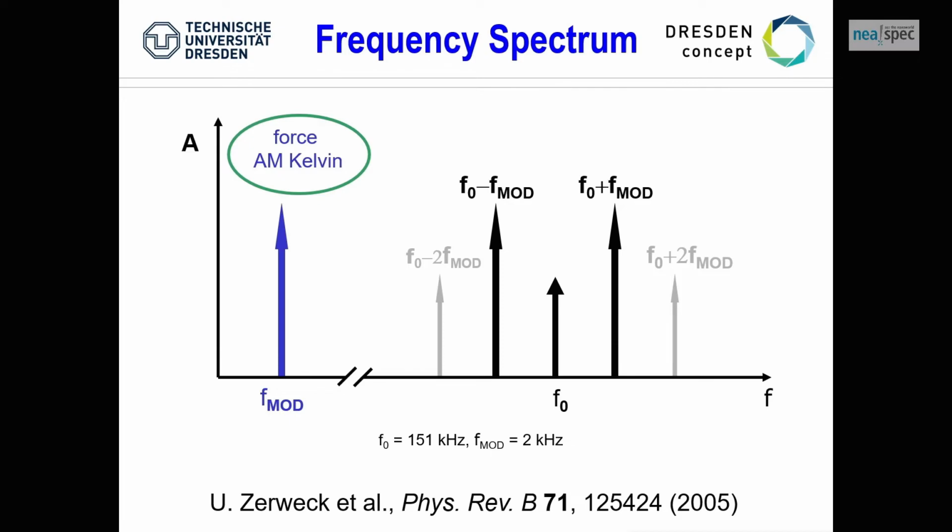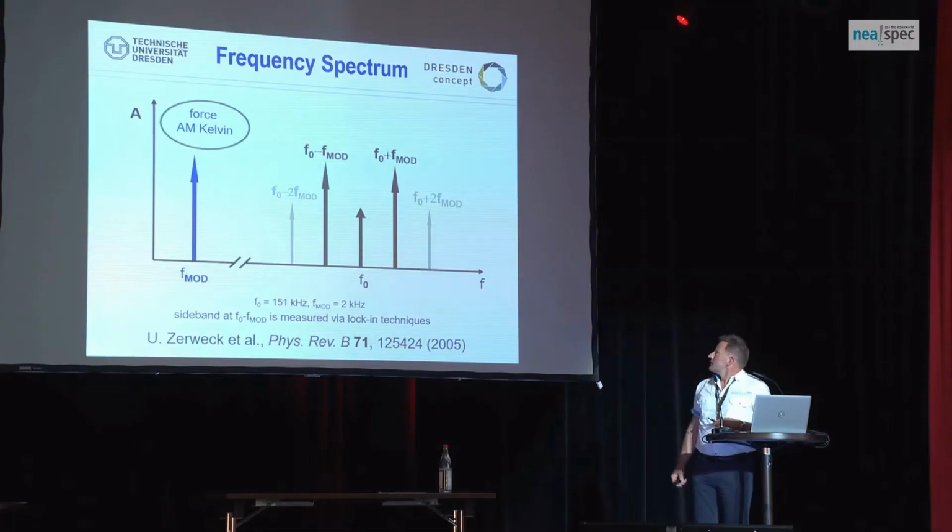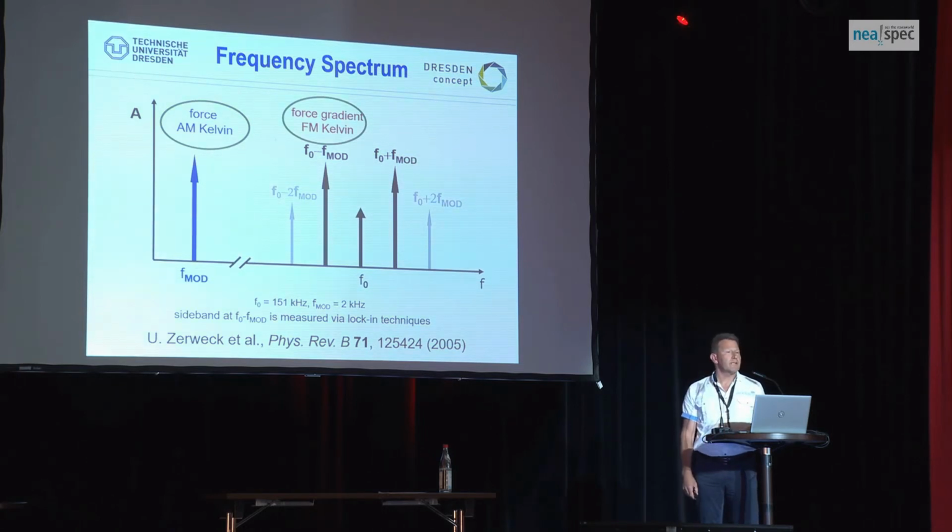What is the benefit of doing this at all? Well, the benefit is we can now really take a mimic, and there's some really modern type of lock-ins, FPGA programming, by really selecting that peak, for instance. We go now for measuring the force gradient rather than actually the electrostatic force. And why is this important? You know the force gradient is strongest at the tip apex rather than at the cantilever. And that's exactly increasing the resolution and the quantitative interpretation by orders of magnitude.